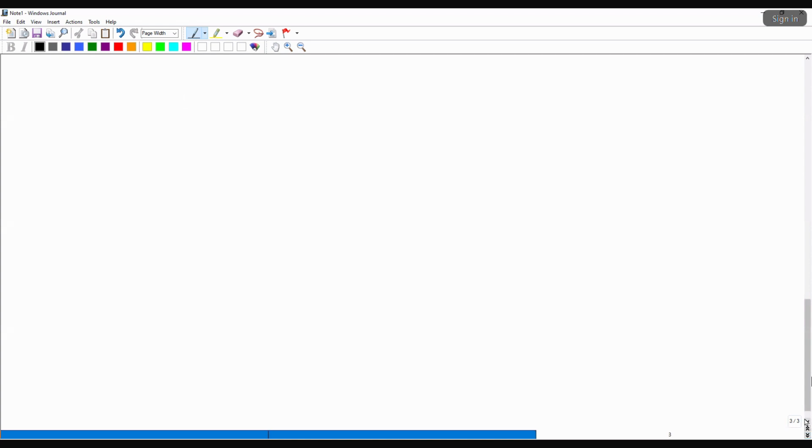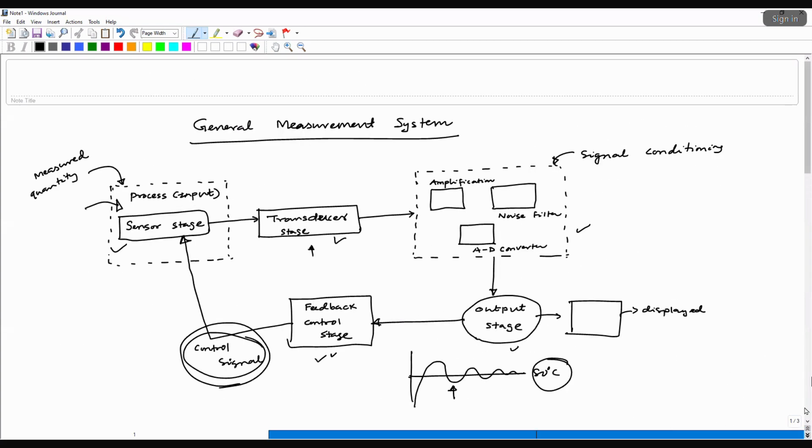Sir, I have a question. Signal conditioning effectively would only be like a filtering process, right? It's to ensure that the final input is devoid of any noise. Yes, so many times the signal that you get is at a very low level and you are not able to really appreciate it, so you can do amplification sometimes. In real systems, sometimes the data is very noisy, so you need to put some thresholding to make sure the noise is filtered from the data.